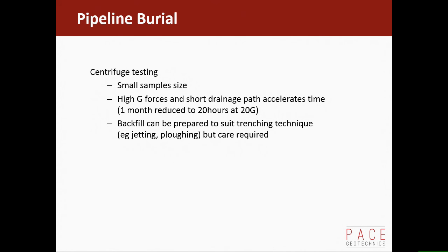So 20 hours at 20G is equivalent to 1 month, 400 hours. Is that right? Yeah. So we model a shorter time period much more quickly, and therefore model the consolidation of the clay. So it's very useful, particularly if we're doing some jetting or backfilling in soft clay soils, that we can model it at a small scale and in a quick time period.